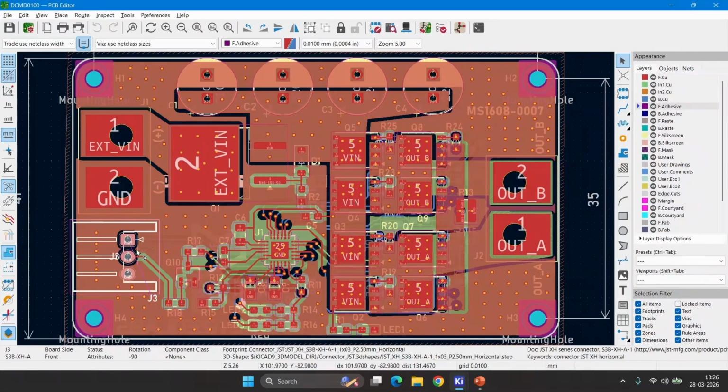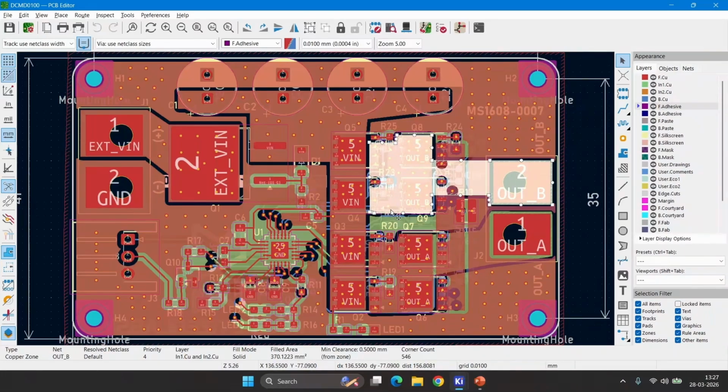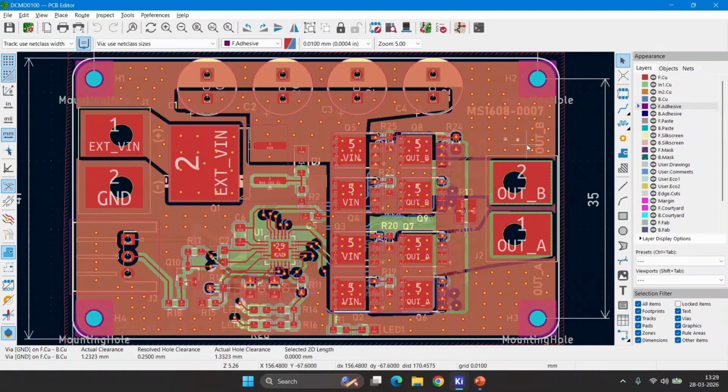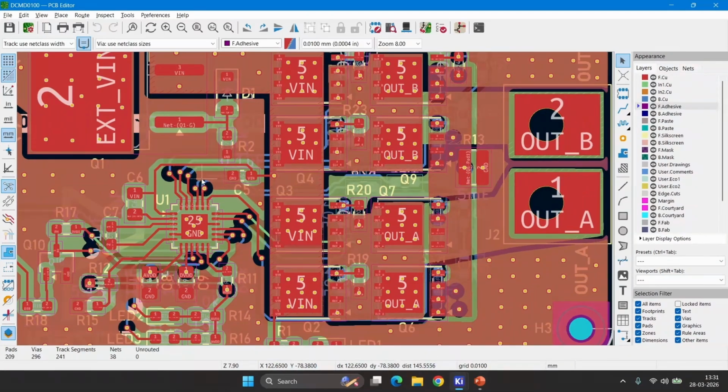And then the signal input connector, PWM and direction. PWM is directly connected to the H-bridge controller IC. Direction pin is going through the inverter circuit and to the H-bridge controller. Fault indication LEDs, power indication LED. To support the high current capability, we have used 4 layer stackup. The output connector is connected to the H-bridge circuit via internal layers. We have provided enough number of thermal vias to support the power dissipation and the temperature regulation of the board. This current sense resistor is just placed near to the low side MOSFETs of the H-bridge and routed to the H-bridge controller via differential Kelvin sense routing.